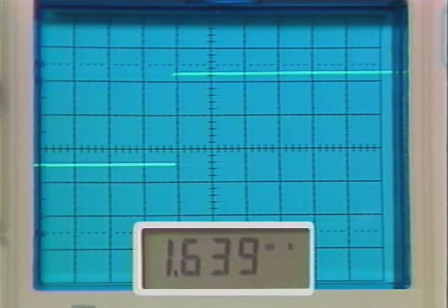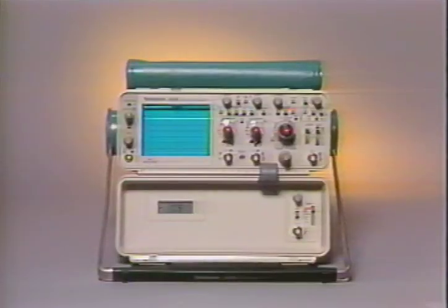This delayed sweep measurement method removes many error sources, such as misreading delay time dials or the A sweep speed, or making subtraction errors. If you have questions about operating the 2335 or 2336, consult the operator's manual. The manual also contains many measurement and application tips.